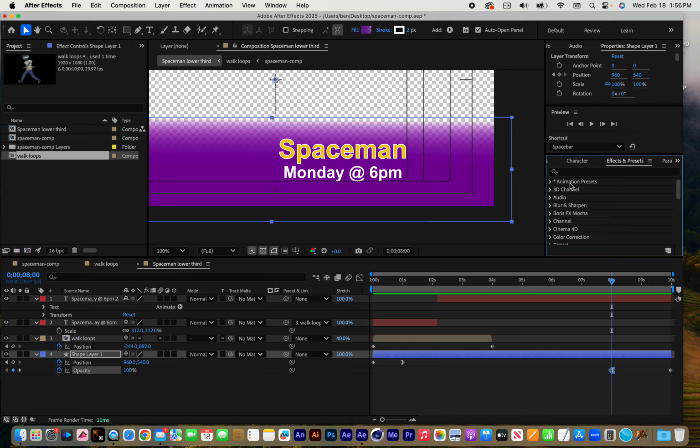And when you're getting started with text in this program, the animation presets for text are a great place to start. So I'll open up that animation presets, find the text group, and there's a group called Animate In and a group called Animate Out. And these are both very useful for doing title work.